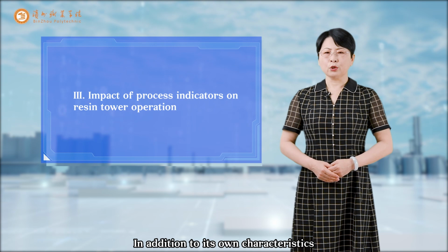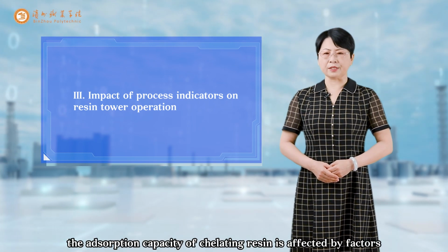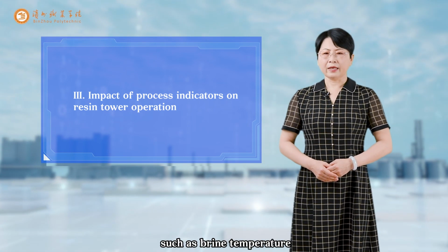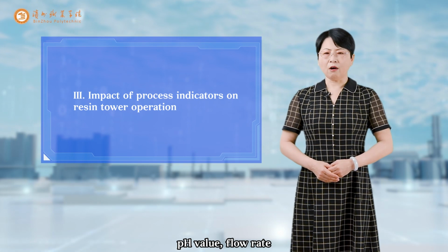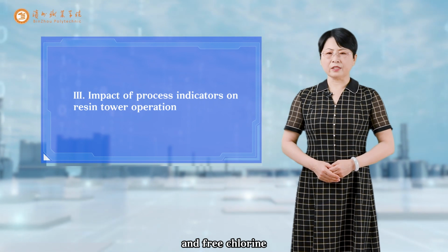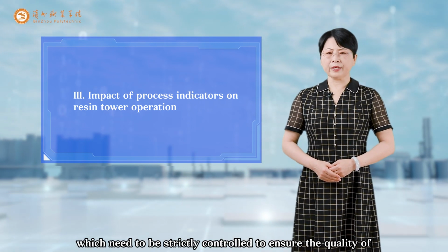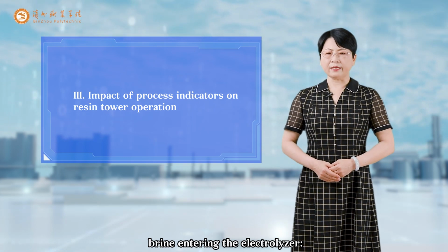High impact of process parameters on resin tower operation. In addition to its own characteristics, the adsorption capacity of chelating resin is affected by factors such as brine temperature, pH value, flow rate, calcium and magnesium ion content, and free chlorine, which need to be strictly controlled to ensure the quality of brine entering the electrolyzer.